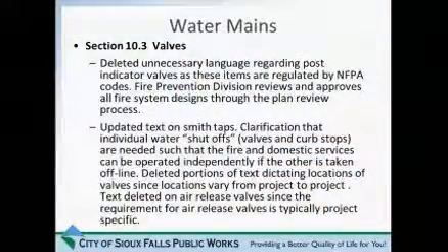Section 3, under valves, we had some more information in there on post-indicator valves. Post-indicator valves are valves that are located outside of buildings that have a post on them above the valve that has a glass window that indicates to the firefighters whether or not the valve is open into the sprinkler riser room.